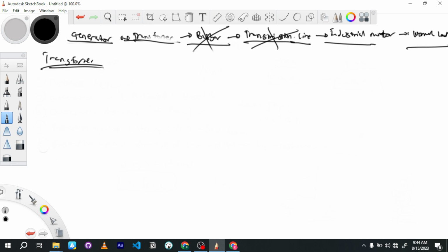Right. So this is CT1 and this is CT2. This is CB A, and this is CB B. If you trip only A alone, you've cut supply off, but you've not isolated the units. Unit protection requires cutting off A and then B.